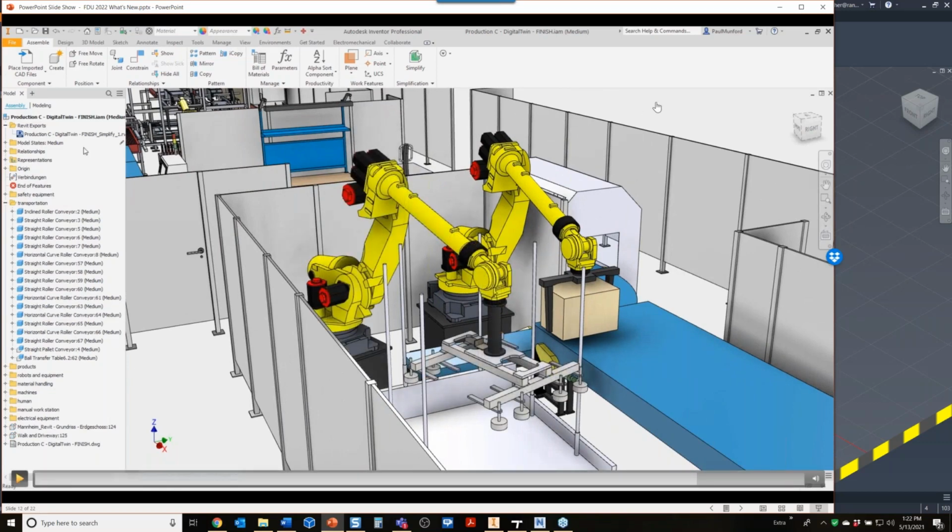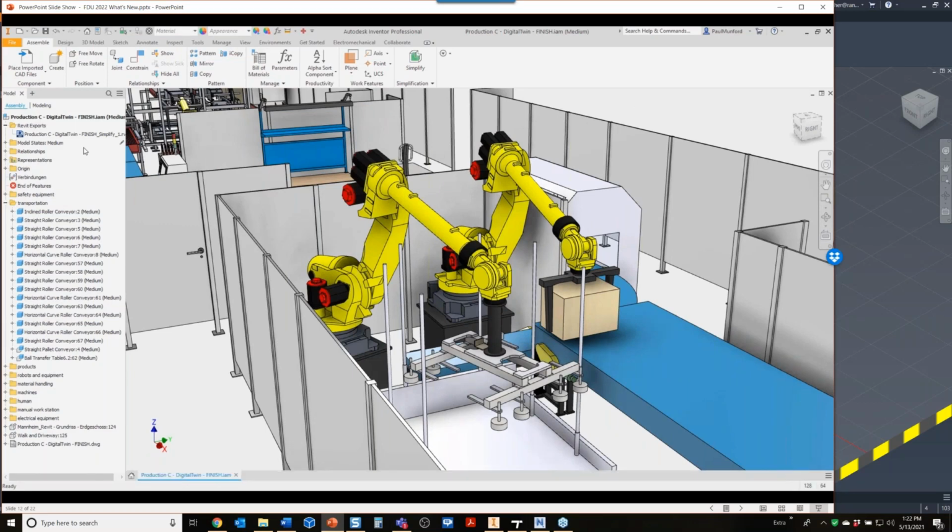All right. There are some issues about updating. On the Inventor side, if you want to update something that you've exported to Revit, you simply need to re-export it. Your models that you do export to Revit, there'll be a link in the browser that shows it as a Revit exported file. You just have to re-export it with the new information and update the Revit file accordingly. It's not automatic, but there are some nice little indications there.